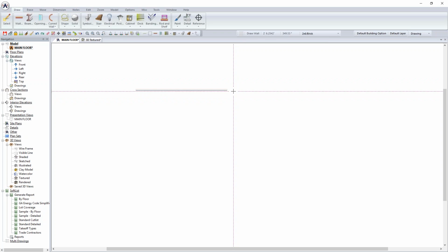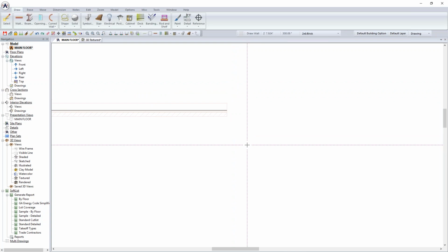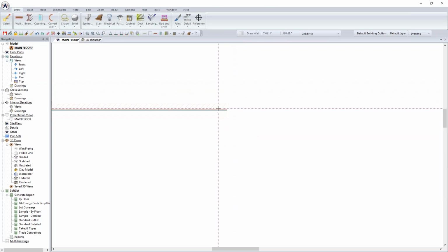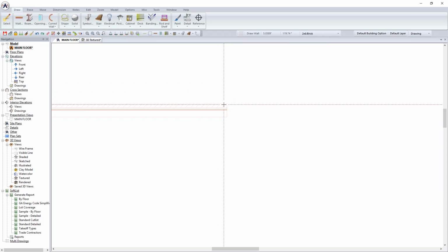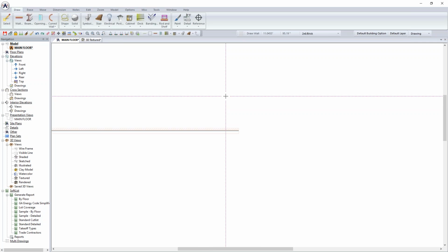and depending on whether I move my cursor up or down, the brick texture is following. And if I just zoom that in a little bit so you can see it, right now the cursor is below the black line that represents the midpoint of this wall, so brick is going to be placed towards the bottom of the screen. And if I move my cursor above that black line, it's going to put the brick facing towards the top. So it's a 3-click process.